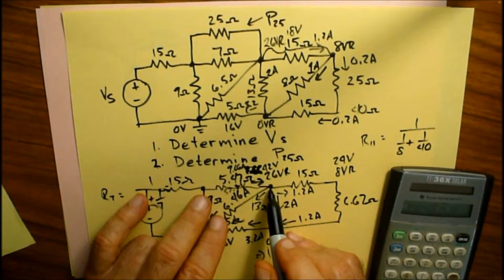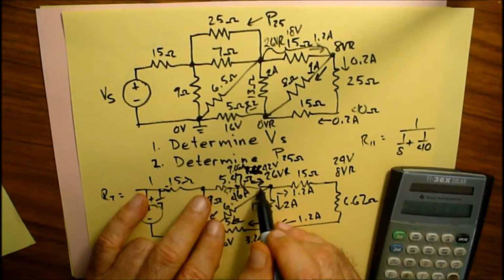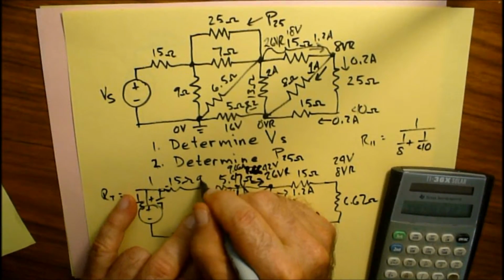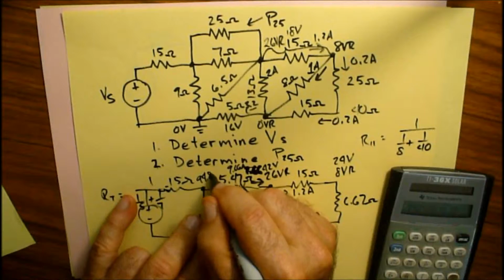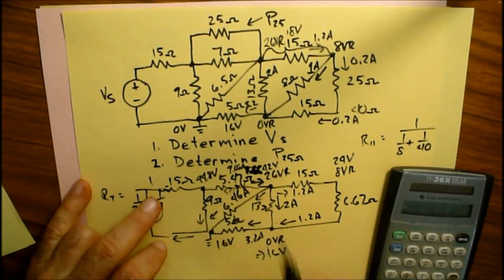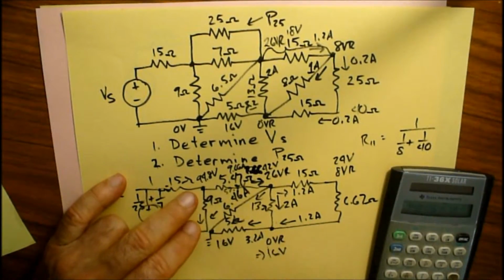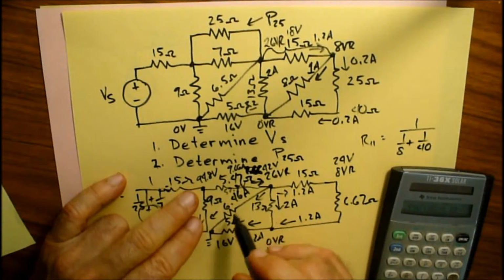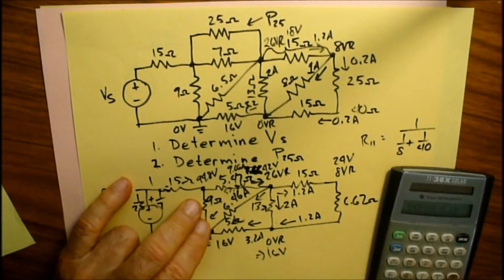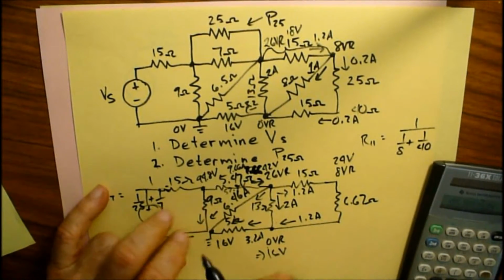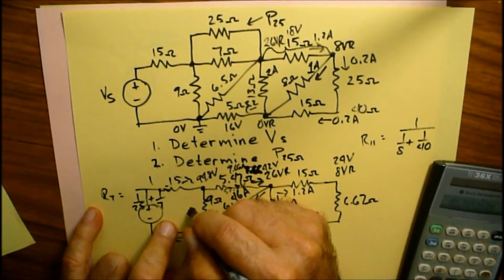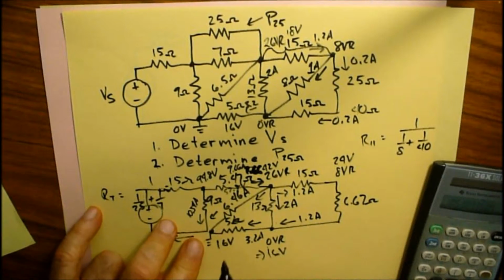across this resistor. But the current's going from high to low, so we add that to this 42 volts, and that gives us 94.8 volts right here at this point. Okay, so 94.8 volts, and here I have a 9 ohm resistor, so divide by 9, and that gives me 10.54 amperes going this direction.